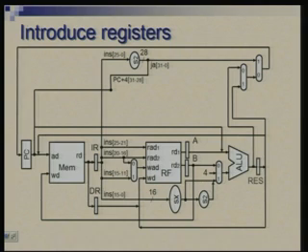Then there is a register which we call RES or the result, which comes out of the ALU, and here I have made the distinction that the PC plus 4 value is immediately going to the PC from the ALU output. So, it is getting stored, but getting stored in this PC.